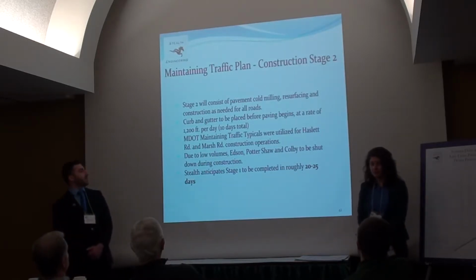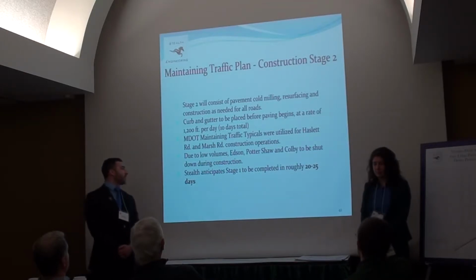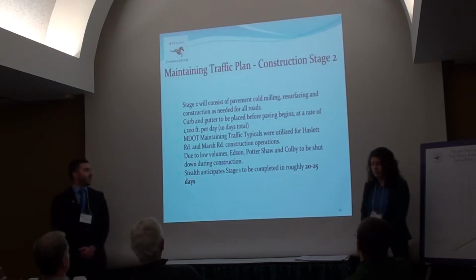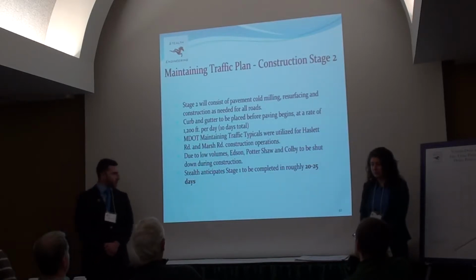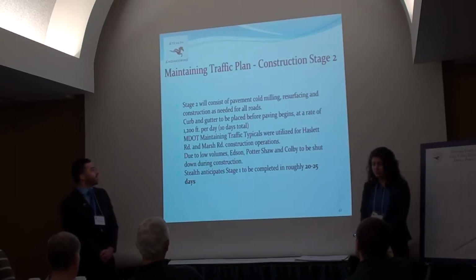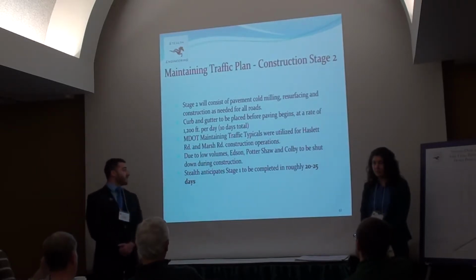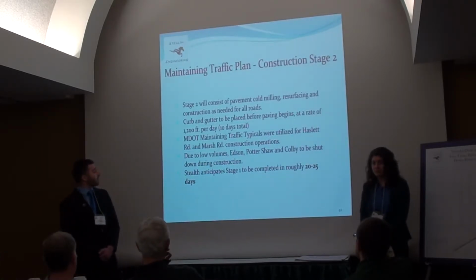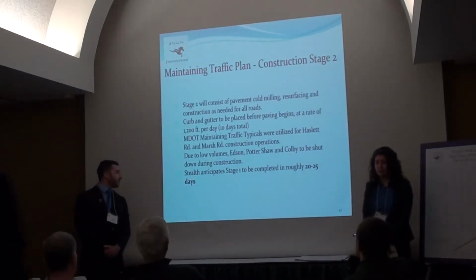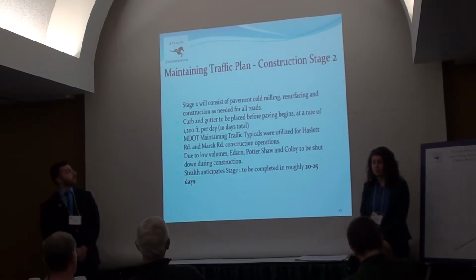MDOT maintaining traffic typicals were utilized for the arterial roadways, Hazlet Road and Marsh Road. And due to low volumes that were determined earlier for Edson, Potter, Shaw, and Colby Streets, it was determined that it would be possible to shut these down completely during paving operations. And details pertaining to this decision will be discussed further. All this considered, we anticipate stage 2 to be completed in roughly 20 to 25 days.